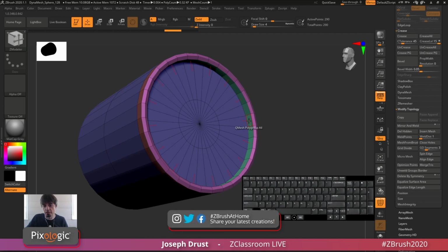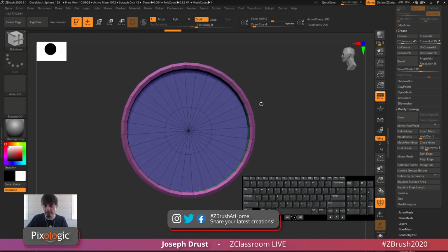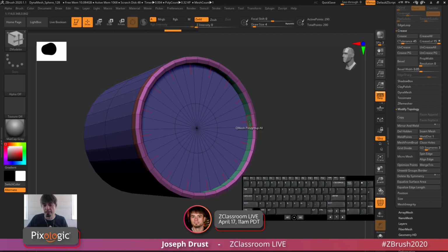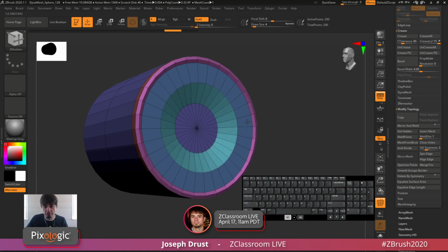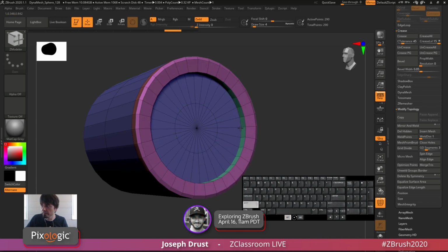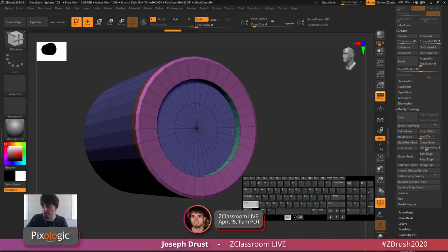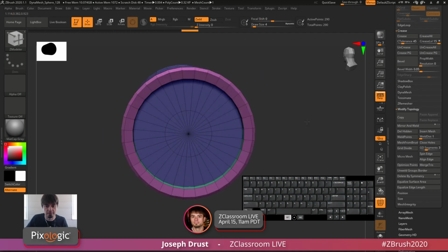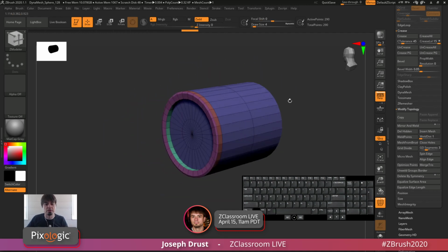Now with this Q-mesh action in this radial format, I can also use that modifier shift, which is going to perform that move. And this is handy if, say, I did this design through here, and then I decided, hey, I want this to be a little bit thicker. So I can come across this inner polygroup, click and drag, and as I'm dragging, I can hold down Shift, and this is now going to do this kind of move. So it's moving that face instead of welding it or extruding it. And now I can tailor that depth. So I can make this smaller instead of larger, right? So I can get it to that size now. So you can come through and play just with that stuff.